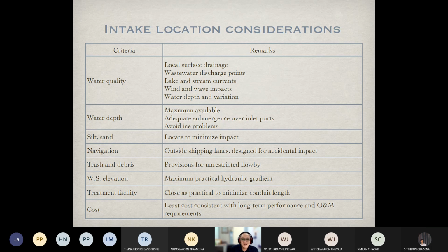They actually take the water from the Mae Klong Dam, which is 100-something kilometers away from the plant, and the water is transported along canals like Klong Phapha. The elevation of the intake facilities is higher, I'm not sure, but a few hundred meters higher than the elevation of the Mahasawat water treatment plant, so that during water transportation we don't need pumping facilities to lift up the head of the water.